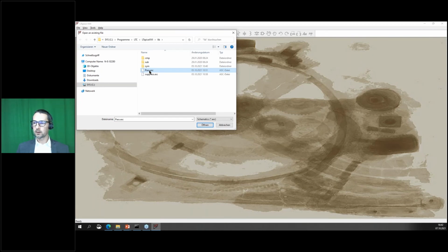For the measurement of the crosstalk suppression, we needed to use 2 termination resistances at the end of the transmission line to be able to measure 2 tracks at the same time: one where we put the signal on and one where we measure the impact of the signal. That's why we have 2 different setups here. Let's start with the first one for the insertion loss and the matching.